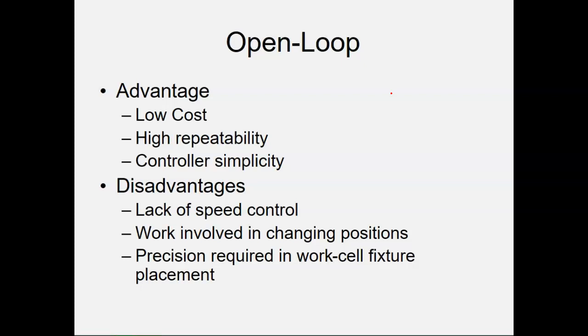However, you don't really have control of the speed the robot moves at. There's a lot of work if you have to change the position, because you're going to have to finesse it six ways to Sunday, right? And precision work in work cell fixture placement, in other words, you cannot shift anything in this robot's work area, or it will be thrown off for a very long time until you can finally get it dialed back in. That makes sense to everybody?